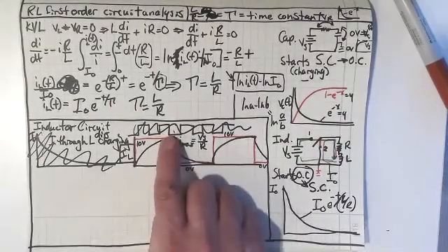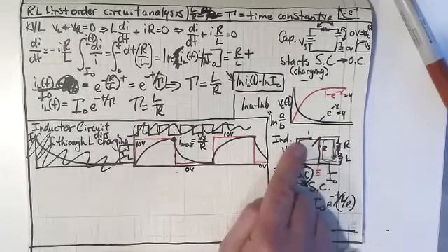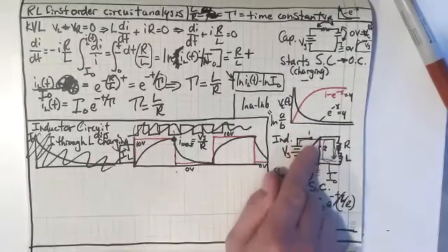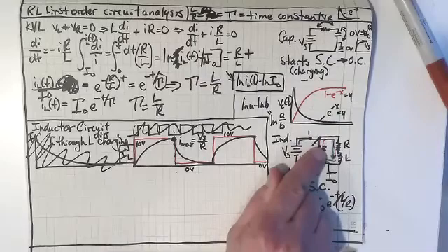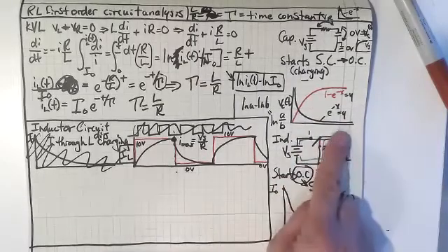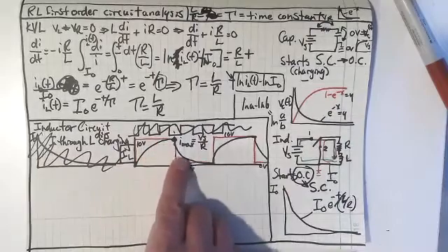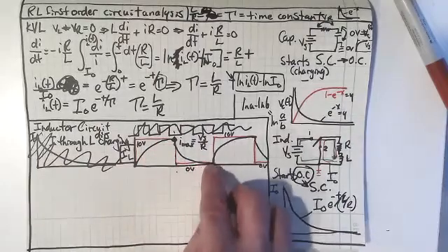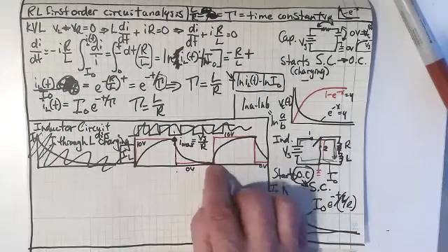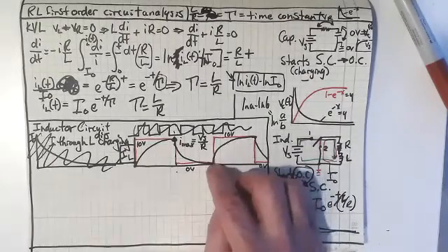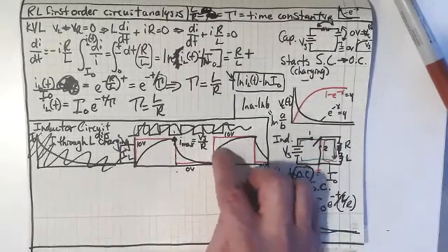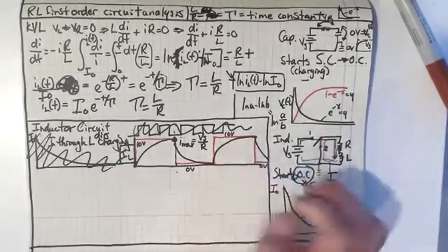Well, if I was to take that right out of there by swinging this pendulum over to 2, then I'm going to start discharging just like I showed over here, and we're going to have the current slowly dissipate down too. And if that's long enough, over 5 or 6 time constants, then it's going to go very close to 0, and we're going to start all over again. Does everyone see how that works?